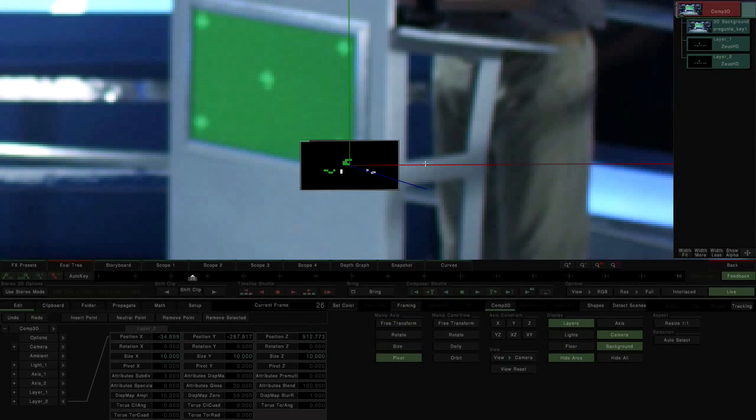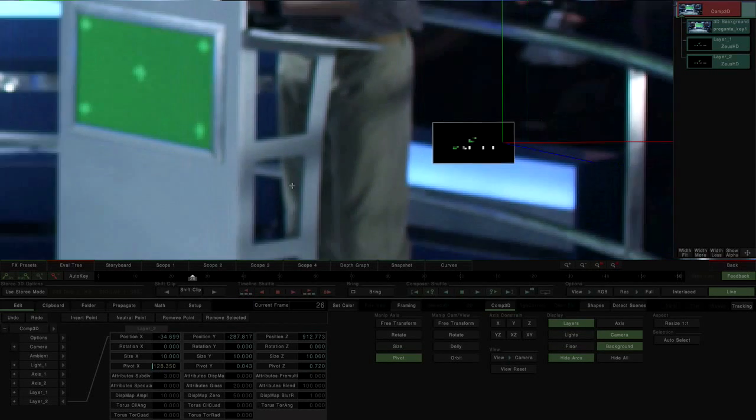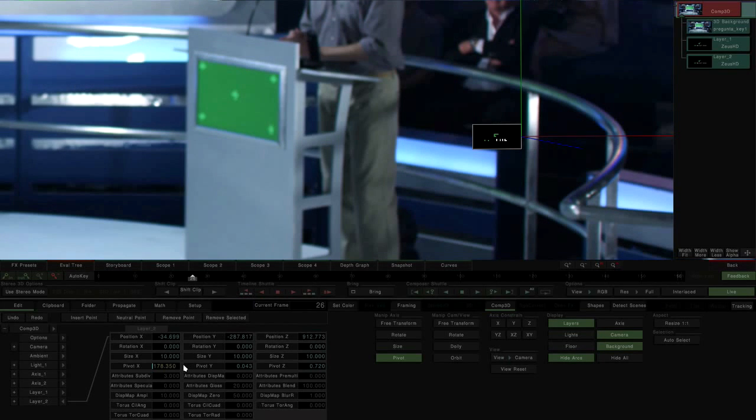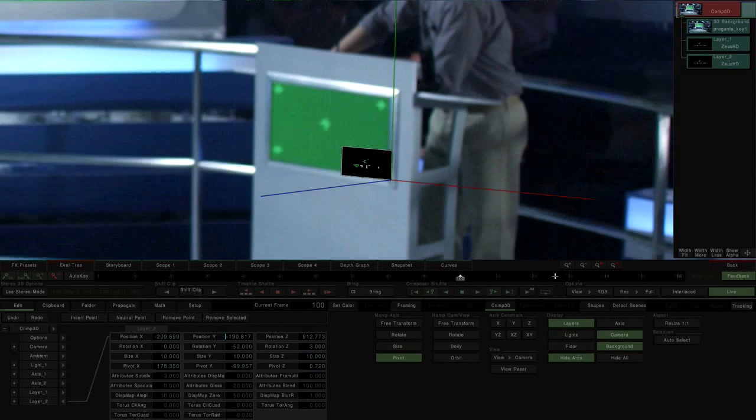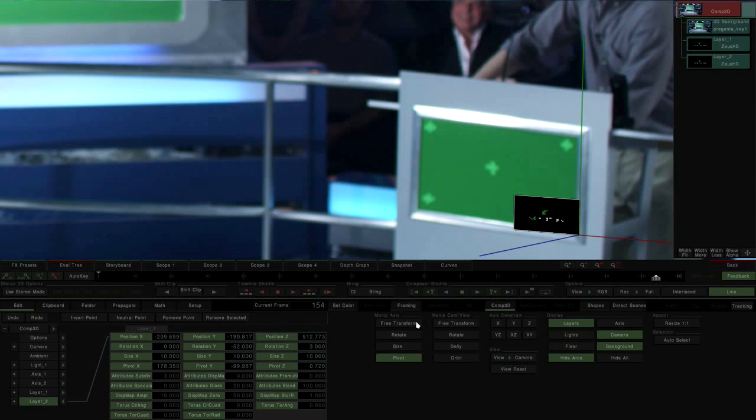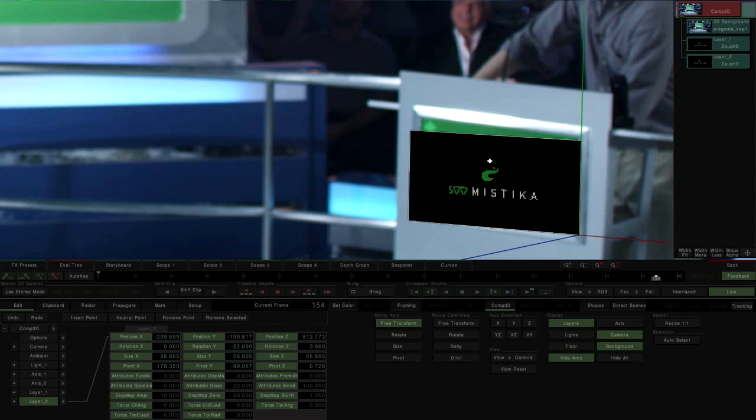We go to the small screen to compose, to finalize the position of the screen. It's important first to define the pivot point, since the tracking obtained was from the point located on the right, so the pivot point must be set on the right. To compensate for the relocating of the pivot, we move the object towards the left, making the right edge of the screen to be composed coincide with the original right edge. Then we rotate the layer in 3D until we position it where we want it. This is one of the most complicated tasks.